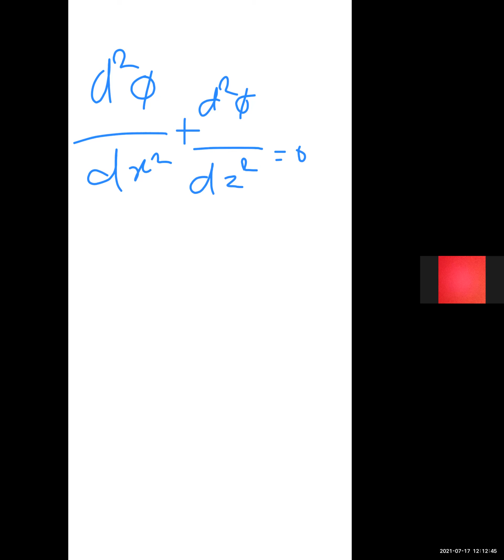The streamline represents the path along which the water flows through the subsoil, and every particle entering the soil at a given point upstream of the structure will trace out its own path, which represents a streamline. The first streamline follows the bottom contour of the structure and is the same as the oblique path of creep.